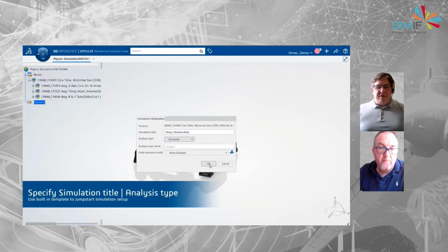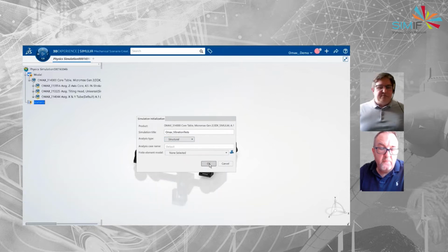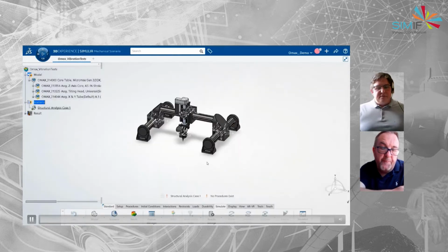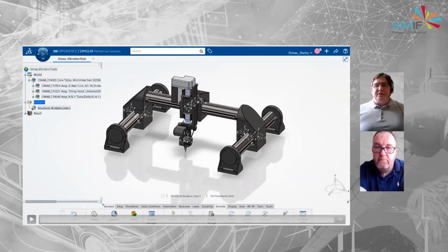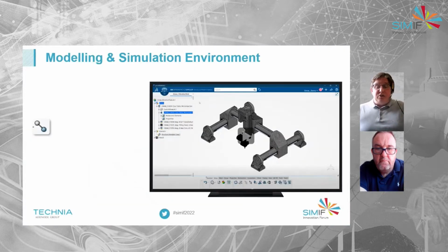So the first study that we're going to create is just a structural one. So what are you testing for here? What we're going to do first off is literally build this as a subassembly and make sure it doesn't fall apart, to be oversimplistic with it. We've got a whole host of different components that are all going to come together, and we want to make sure that they're all up to spec. This is a precision bit of kit, and we want to make sure that precision isn't affected by the extrusion being too thin, and it ends up with a bit of flex.